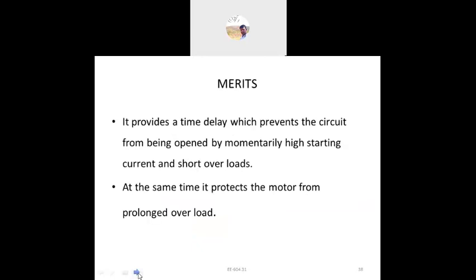Some of the merits of thermal relays: they provide a time delay which prevents the circuit from being opened by a momentarily high starting current or a short one. So it will not open instantly; it will take some time.